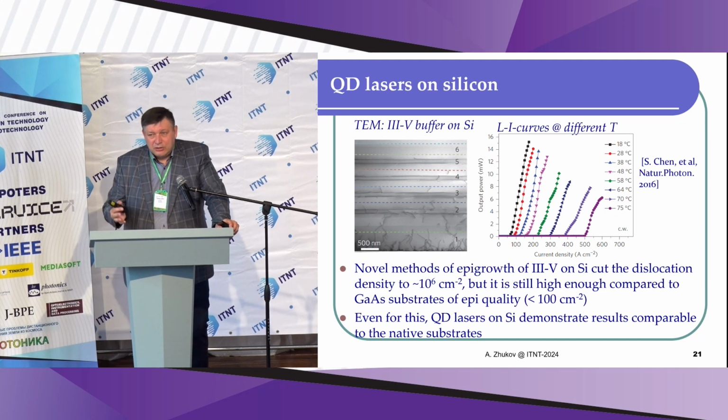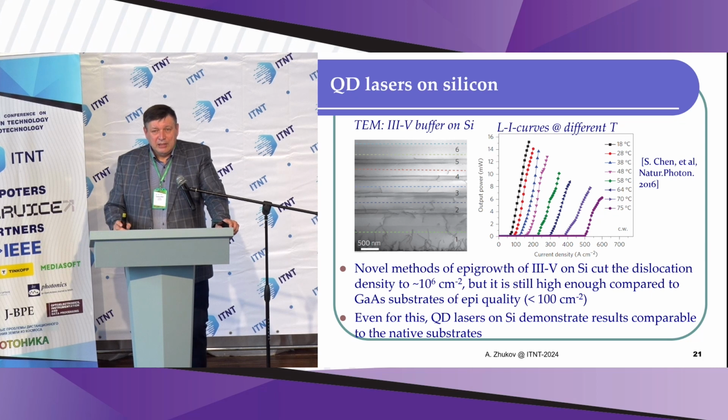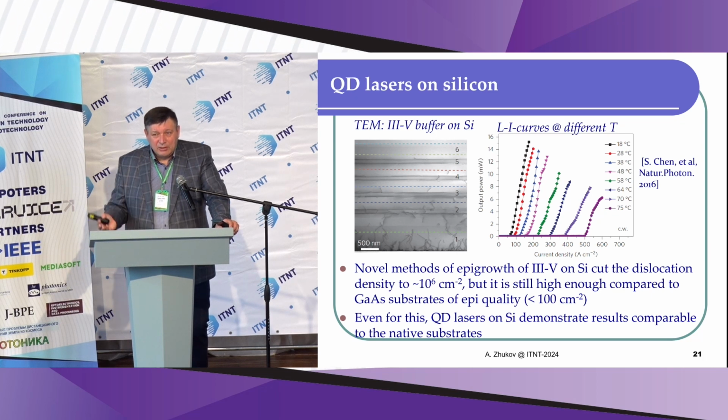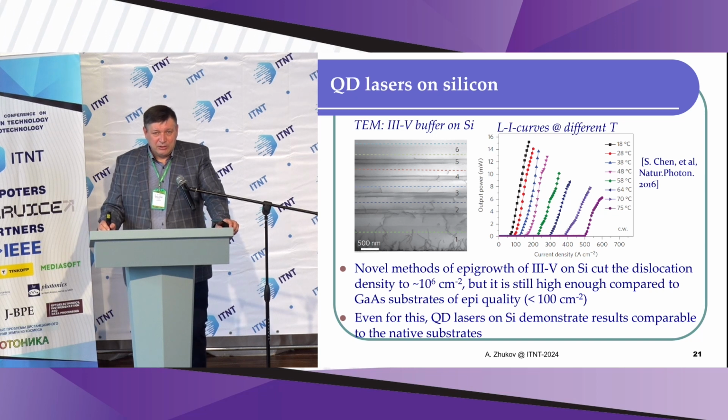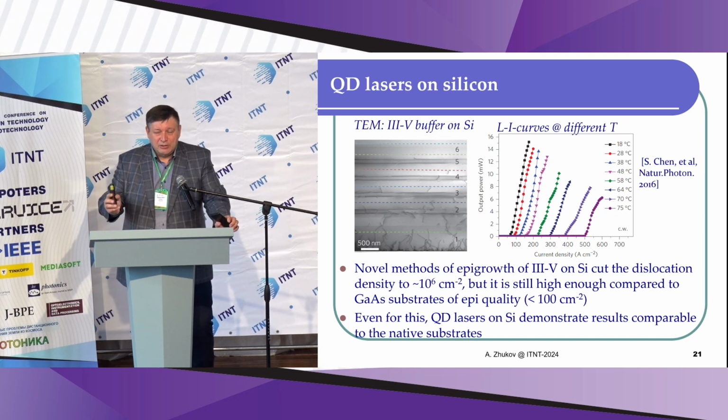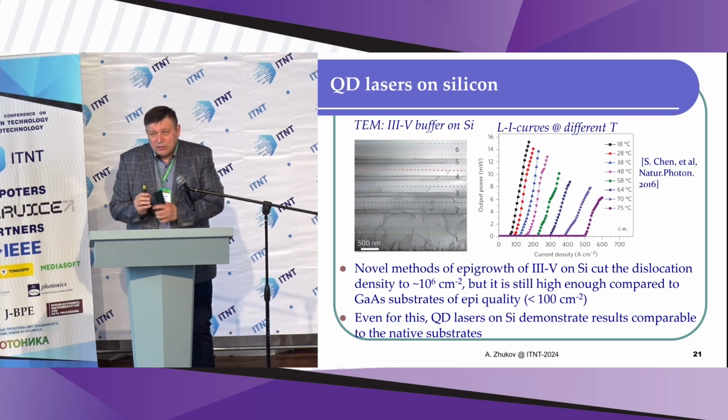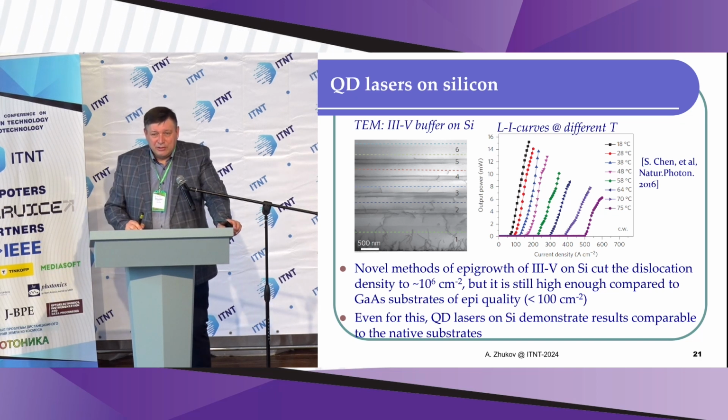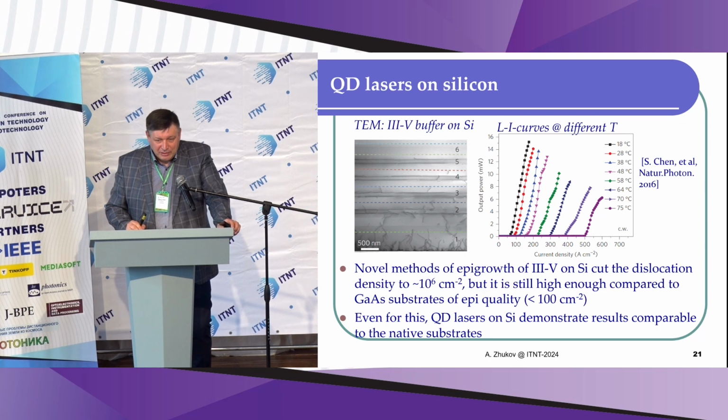For example, silicon is just silicon, and gallium arsenide contains both gallium and arsenic. The epitaxial growth of gallium arsenide on silicon can start from gallium atoms or from arsenic atoms, and when these two domains reach each other, crystalline defects appear.